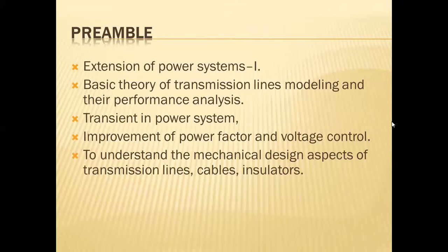The reason for transmission lines operating at very high voltages: for the same power to be transferred, when the voltage level is more, the power loss in the line will be less. Simple calculation by using I square R loss. When the voltage is increased, current decreases. The decrease in current helps in decreasing the power loss in the form of I square R.